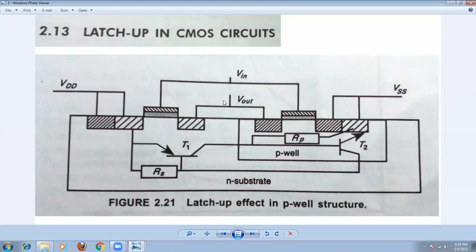That is about the latch up. There exists a silicon control rectifier. This is the same form of resistance, transistors T1, T2, and RP, used like a silicon control rectifier. So remember that one, right? That is about the latch up in the circuit.